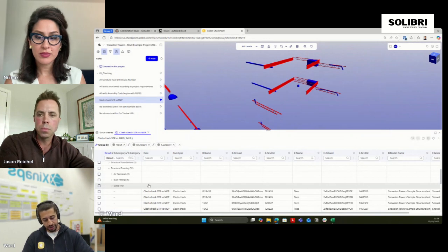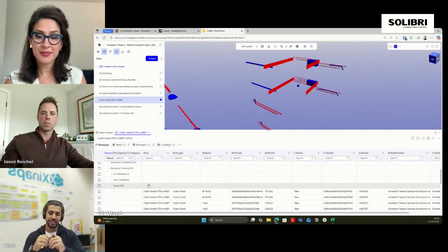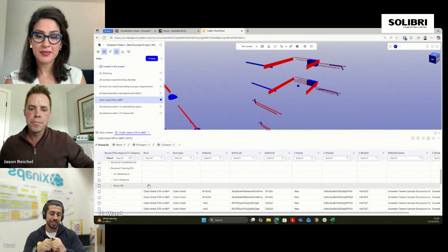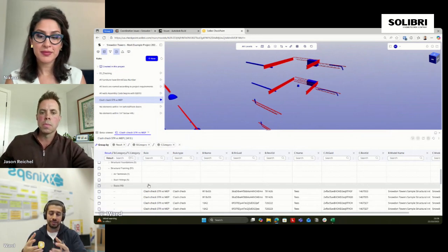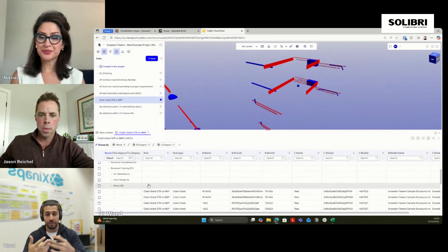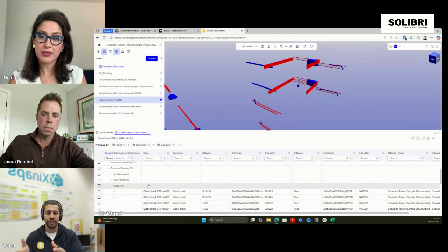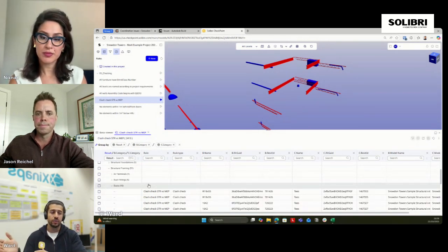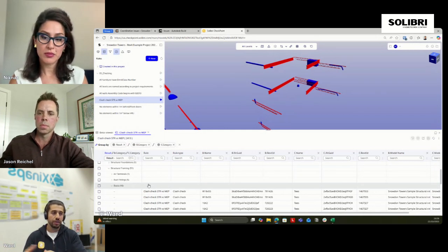Yes. So actually, this brings back all the memories that I had in the industry back in the days when I was a BIM engineer, because truly these clearances were such a headache. So we create them and then we add them to the elements and make sure that they're not intersecting. Sometimes we don't even add them. We just go through the model manually, by observation, and make sure that we have spaces, let's say, for the mechanical equipment, for the doors, for the alarm panels, and so on. We just needed some clearance over there.